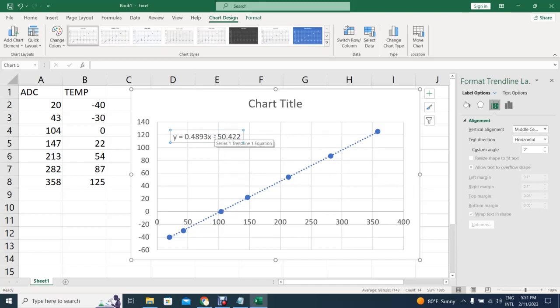And I can definitely use this equation from -40 to 125, and the output will correspond perfectly to the right temperature that we want. For example, if the output is 250 on the ADC, that would be converted to a temperature between 80 and 60 degrees, somewhere here, right? Around the 250 value. So any value that is maintained between, let's say, 20 here and somewhere a little bit below 400, is within the linear range of the instrument. Excellent.